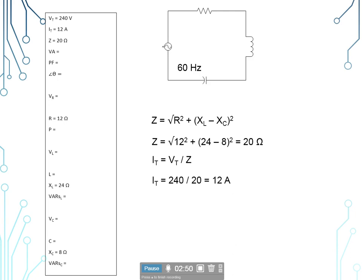Because this is a series circuit and the current remains constant through all components in that circuit, we can say I sub T is equal to I sub R is equal to I sub L is equal to I sub C is equal to that same 12 amps. So we can go ahead and populate all of those with the 12 amps.